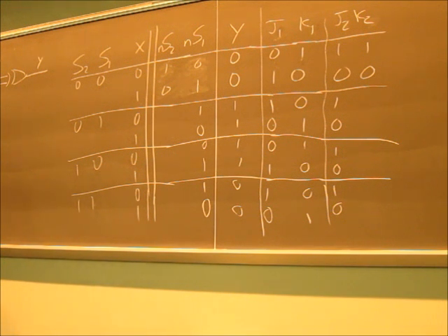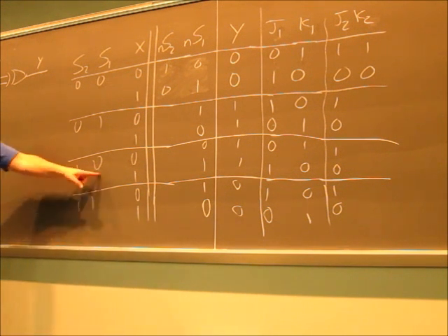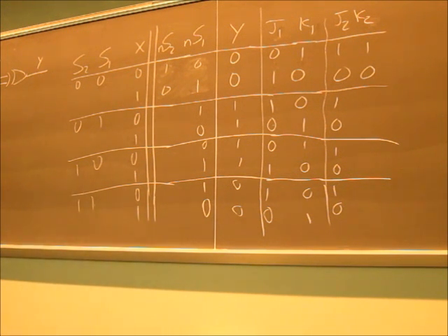If you recognize how the gates function, it will go faster for you when you're doing the circuit. If you look at this and you go, oh my God, I would never figure that out, then don't worry about it. Take the state bits and write them in and follow them through the circuit. It will work.